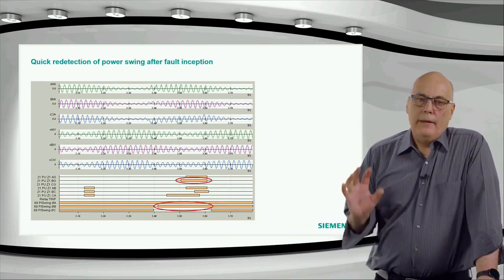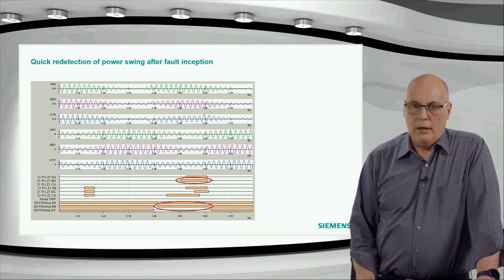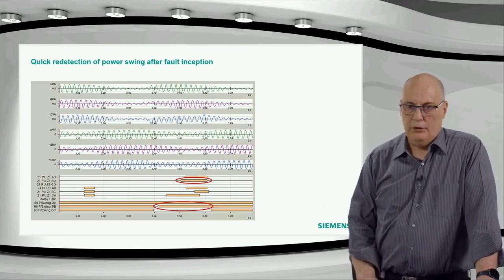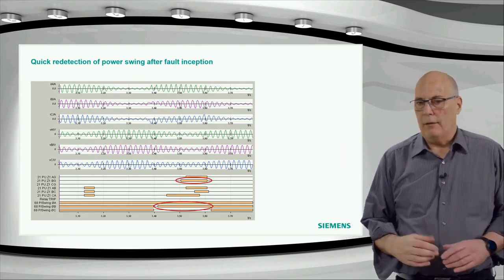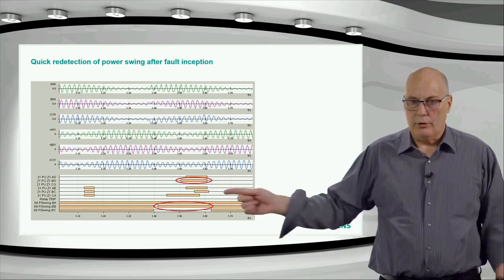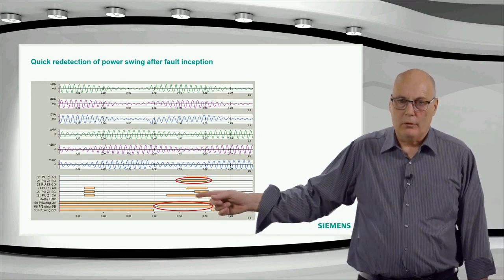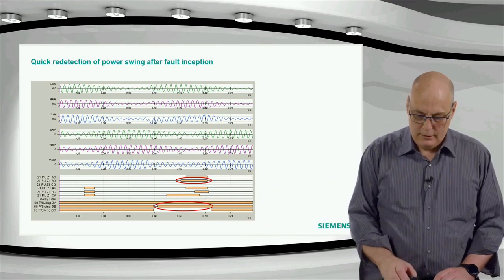Okay. In this model, the tripping was not done to the breaker. Otherwise, the current would have stopped. It would have a single pole dead time here, but unfortunately, the model used at that time did not really trip the breaker. It was to show the zone 1 trip would have come, and on the other phases, the power swing blocking stays on over here. That is clear.